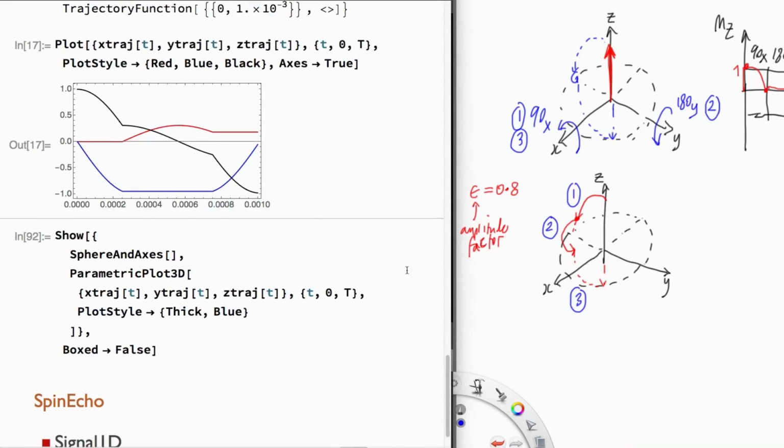So that's done here. So this routine uses a Mathematica routine called Parametric Plot 3D, which plots a trace in three-dimensional space. And without going into the details of how to use it, basically you provide the Parametric Plot 3D routine with three functions which define the x, the y, and the z positions of the points, which should depend on a parameter, in this case time, which runs between two values.